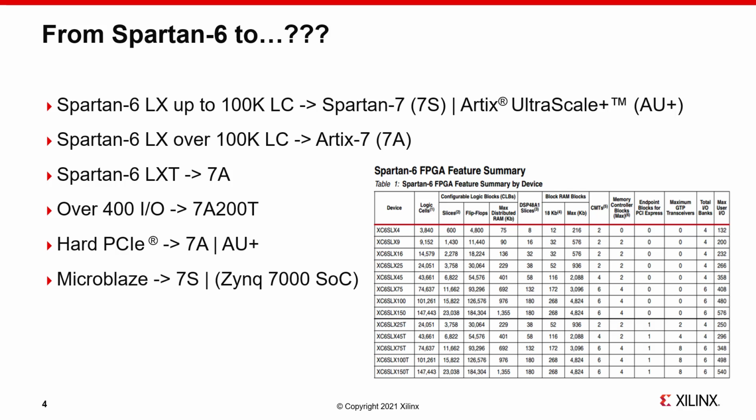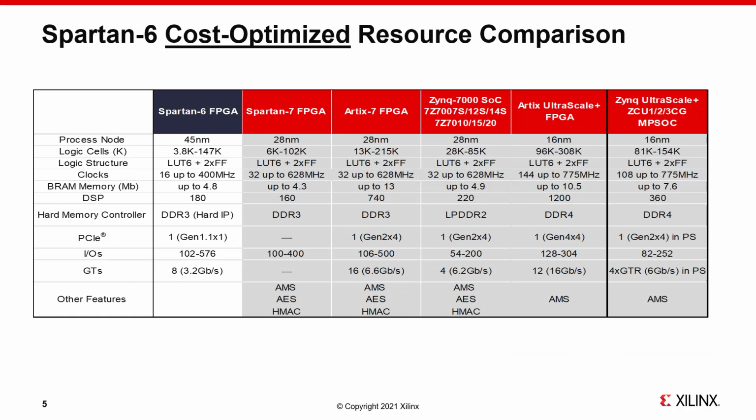Is there a soft microprocessor in the design? If yes, then do we consider remaining with MicroBlaze, or perhaps we move to something like the Zynq-7000 series part? In the end, the design is going to determine the available parts and architecture to target, and we need to consider this upfront to make sure that we're moving in a good direction and don't have to back up and change devices.